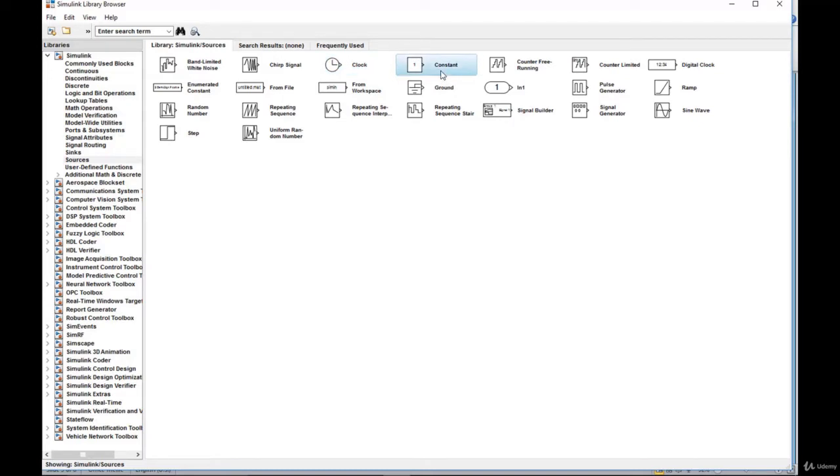You can use time, a constant block, random number, or a random function which works randomly for input, or ramp and pulse generator. Or even if you want a source input that is not in Simulink, but you have defined its code in MATLAB before, you can use this block to recall the code and give it to the system as a block.